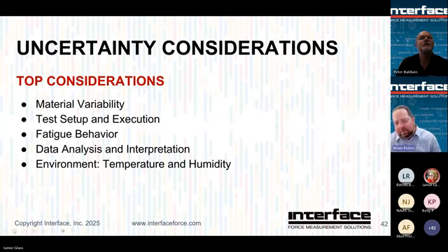Oh, and just in reference to that previous example, we talked about the error influence that can be developing, but you also aren't necessarily testing your product or whatever it might be to the same input forces that you thought you were, right? Usually fatigue testing is a culmination of FEA or other analysis, modal analysis to say, okay, now let's go validate our models that we've developed. Well, again, if you were seeing side loads or introducing bending into your test article that you didn't think you were, it kind of throws a lot of that out the window, right? Because it wasn't in your force case scenario.